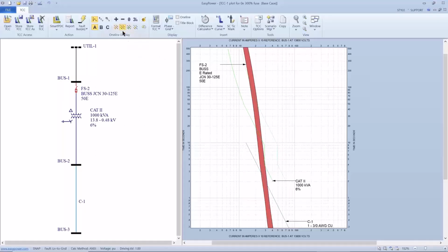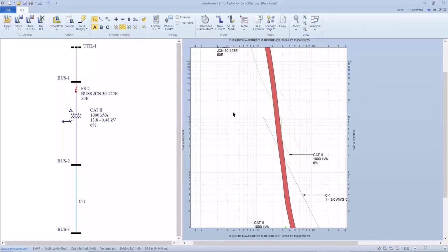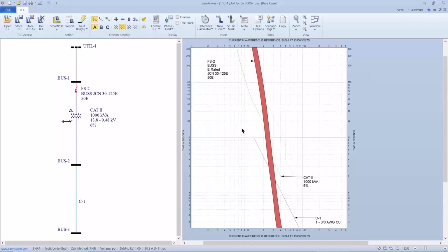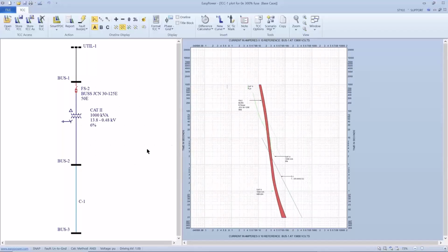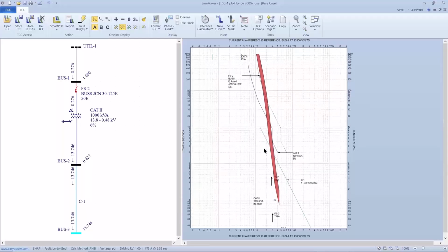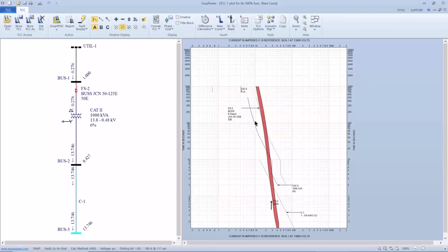If we look at a single line to ground fault, I'm seeing 276 amps in the primary, and in that current here at half cycle, and here at 30 cycles, this shows protection for my frequent fault potentially, but it doesn't have protection for this lower level long-term current.